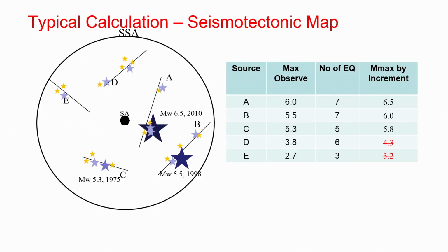So, let us take an area. This is my study area. I have 5 sources. Here I am giving you a typical calculation; do not look exactly at the size of the drawing and the estimation, it is only a typical calculation. This is my seismic study area. In the conventional approach, you do not worry about the seismic study area because there is no guideline. But in my rupture based approach, we selected this based on the past seismic data in the region, intensity map or PGA record, whatever. We have 5 sources A, B, C, D, and in each source we have a different earthquake.